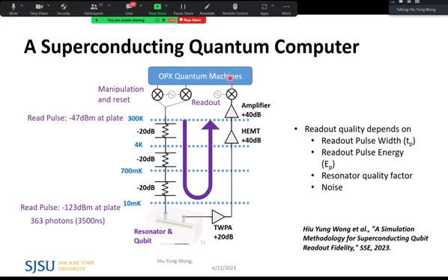What it does is keep generating very high speed pulses. And based on the readouts, it generates other pulses. This microwave pulse will get to the mixer to bring it to the right frequency. And they are at 300 Kelvin. Then we go through attenuators to filter the noise, to reduce the thermal noise. Keep going: 300 Kelvin, 4 Kelvin, 700 millikelvin, 10 millikelvin. So this is in the dilution refrigerator I just mentioned.